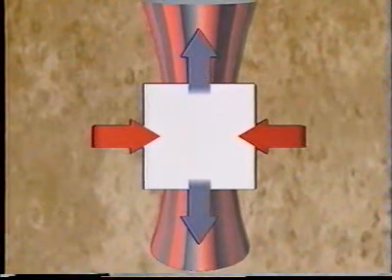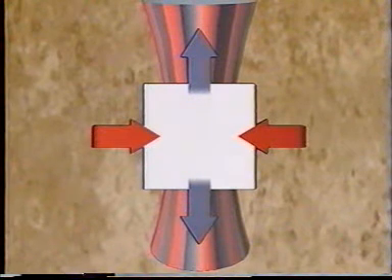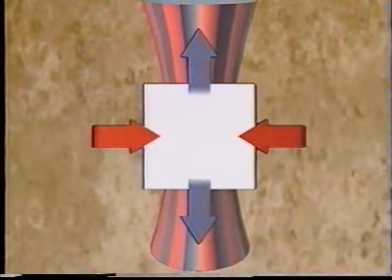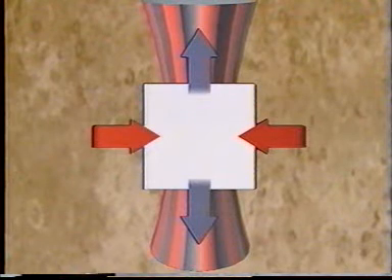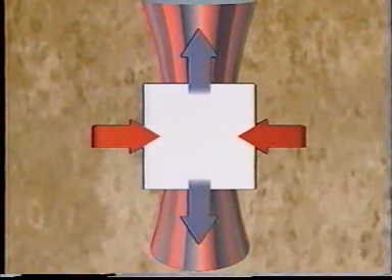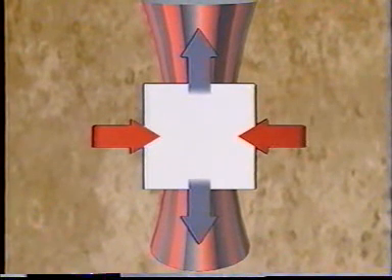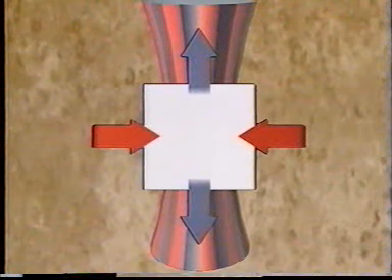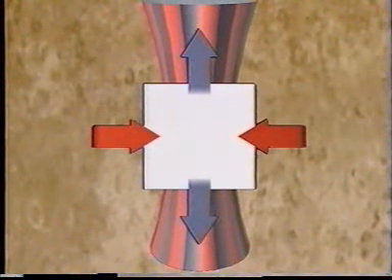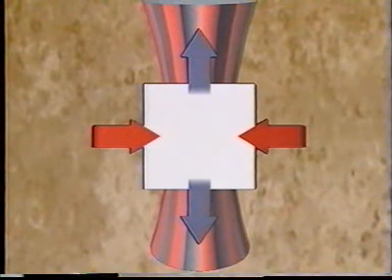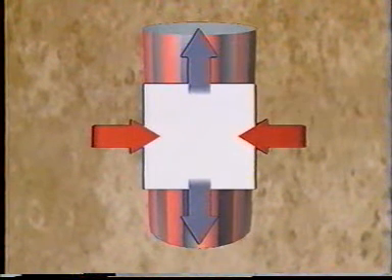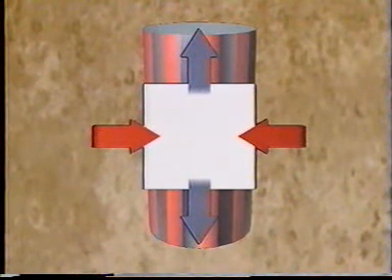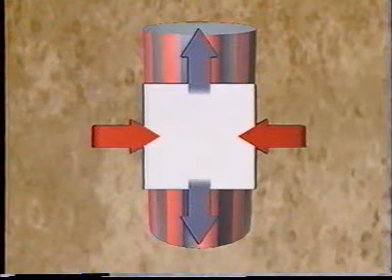As the tensile stress is applied, the part tends to elongate. The part also tends to contract on the sides, creating a compressive stress component inward to the center of the part. The direction of this compressive stress is shown by the compression arrows, perpendicular to the direction of the tensile stress. The free body diagram shows both these stresses, the tensile stress and the compressive stress, applied to the cylinder.